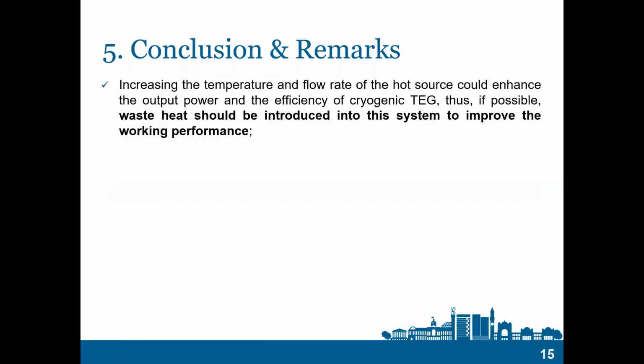Finally, I will give you some conclusions and remarks of this research. First, increasing the temperature and flow rate of the hot source could enhance the output power and the efficiency of the cryogenic TEG heat exchanger. Thus, if possible, waste heat should be introduced into this system to improve the working performance.